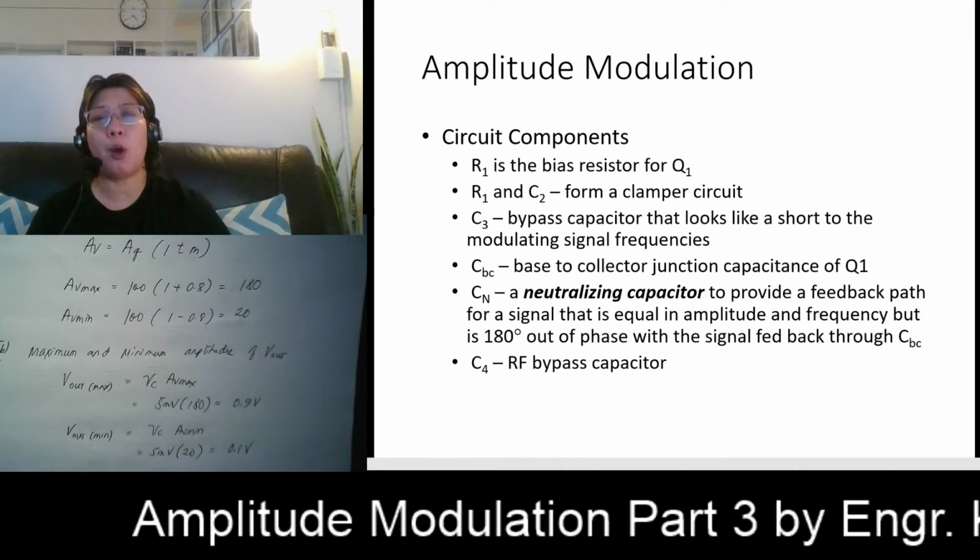As you can see from our previous slides, your IC is in the form of pulses, and those pulses are how the output of a Class C amplifier looks. The shorter the duration, the higher your efficiency. Therefore, Class C has high efficiency.